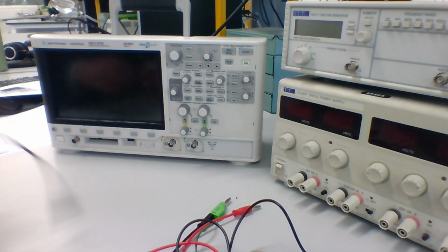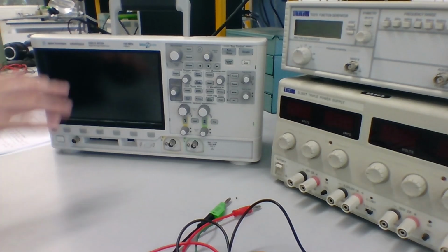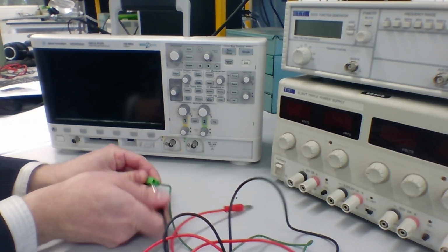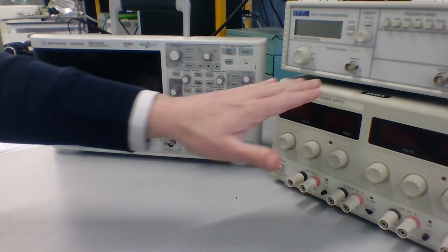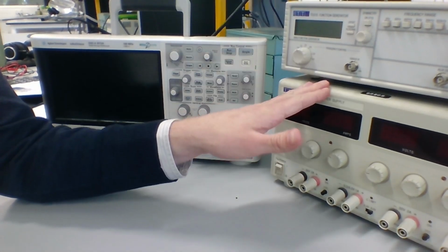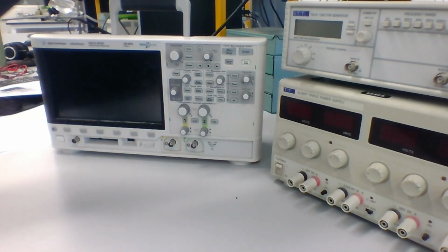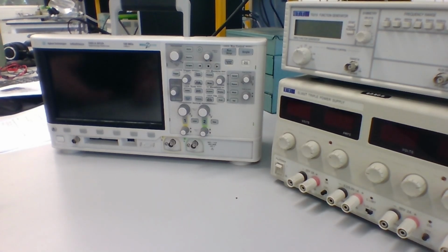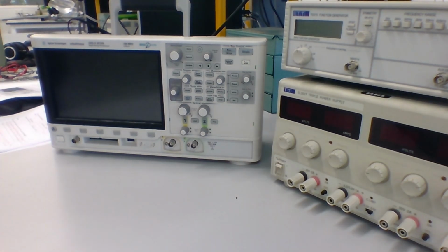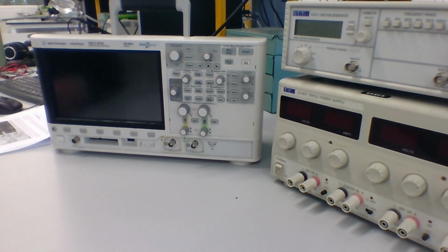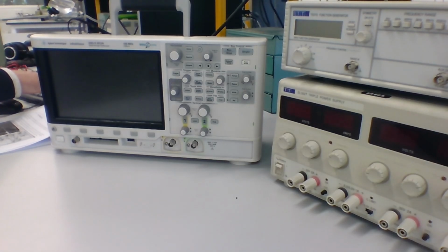The next thing we're going to do is look at another really important piece of test equipment, which is the oscilloscope. So our DC power supply gives us the ability to generate DC voltages and currents, and our multimeter gives us a nice way of measuring DC voltages and currents. We can measure AC ones too, but we only get an RMS value. Our oscilloscope lets us measure things that are actually changing with time and gives us a much more accurate measurement of what's going on in more complex circuits.